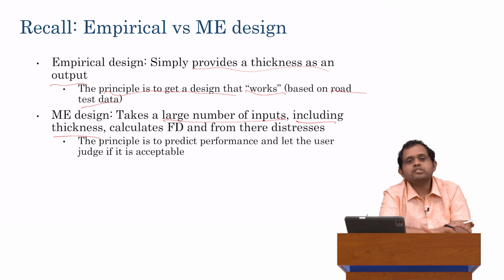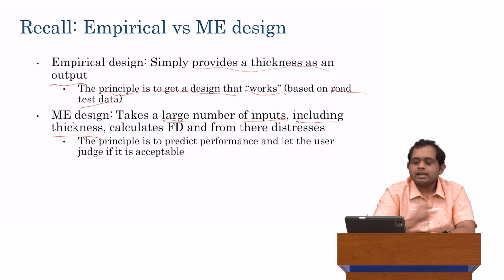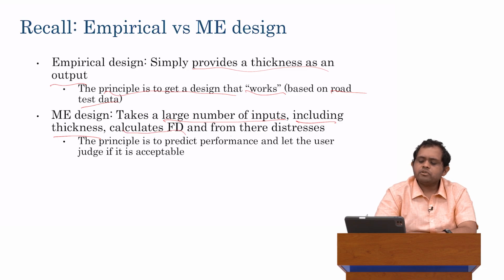So we can choose a thickness. Indeed, we have to specify some trial thickness to start with. And then what ME design does, based on all these inputs, including a trial thickness, it's going to calculate the fatigue damage and from there distress.